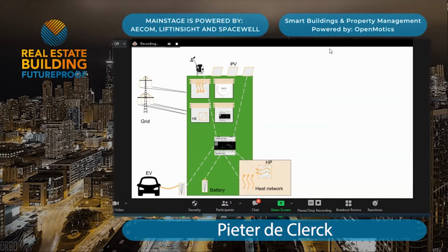But on the other hand, we have installations within every unit, and these need to control assets as well. We have the heat exchanger, which delivers the heat from the heat network to the unit. We have the thermostat for the comfort control, ventilation, etc. For example, for certifications such as BREEAM, certain rules need to be implemented. And by using a central weather station, the individual screens can be controlled in a cost-effective manner, but with respect to the end user, because he can overrule the automatic screens whenever he feels like it. So the energy optimization should never come at the cost of comfort.